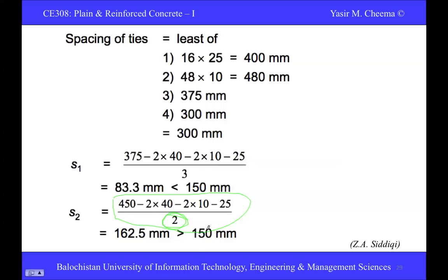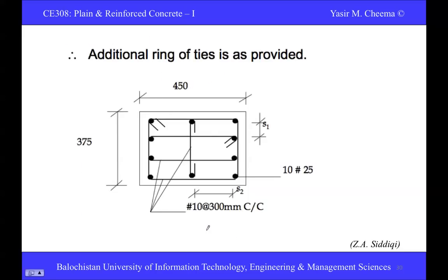As I remember, I think it's slide number 11 that describes the spacing criteria, how much spacing should be there. You can see the spacing criteria at slide number 11 of the same lecture. So here is its arrangement. You see here we provide 3 for the S1. If you remember, we divide it by 3 because we are supposed to provide 4 reinforcements here and 3 spans.